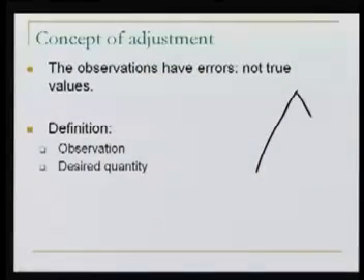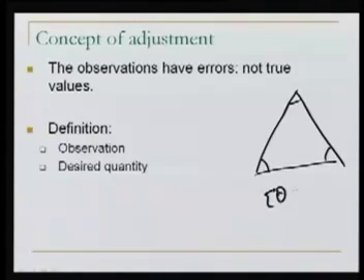Well, now the important thing. We have seen the geometric condition and observation condition. Also, we have seen that the observations which we are taking in the field do not satisfy these conditions. But that is not desirable. We have a triangle in the field, and for this triangle we observe these 3 angles, and now we find that the sum of these angles is not equal to 180. Can we live with that?